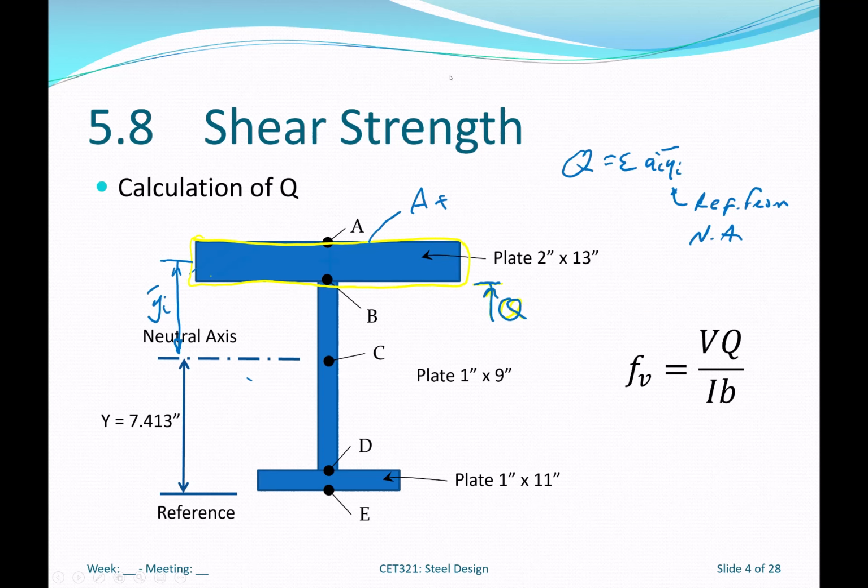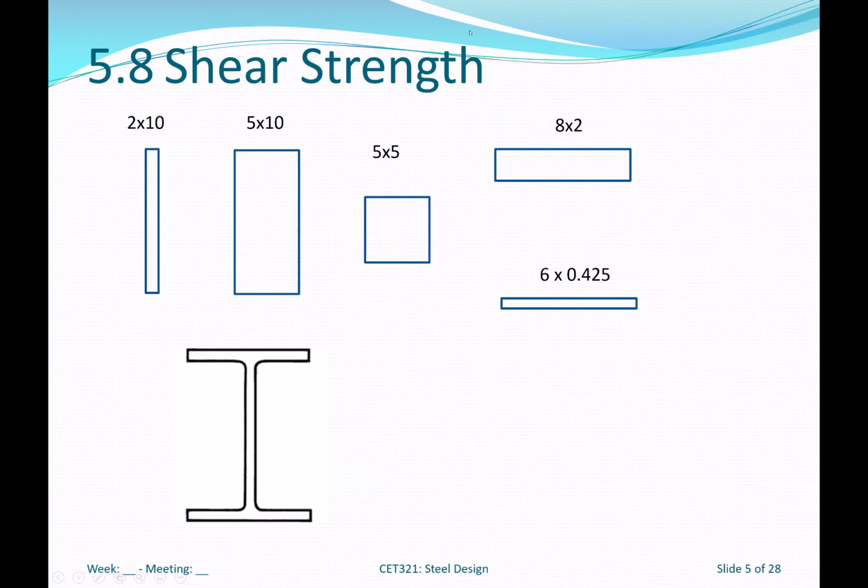So that VQ over I equation, right? Shear stress VQ over I B. Okay. B being the width. Sometimes you'll see tau equals VQ over I t. Okay, it's really just the width of the shape at the point of calculating shear stress. Okay, we've used that equation and we'll continue to use it or base our discussion on it, but you need to be aware of the limitations.